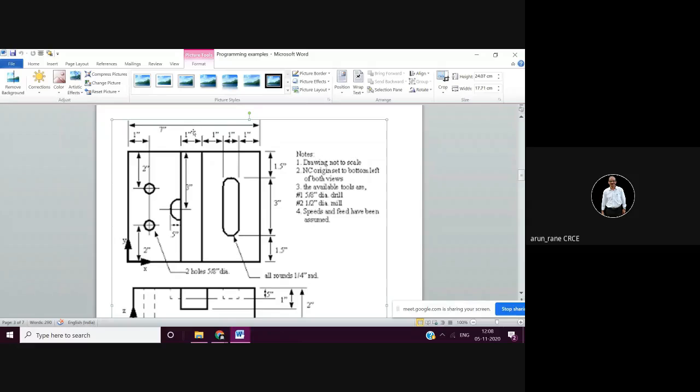Okay. Then I will bring the cutter here. What is this distance? Let us assume that this is given as 3 inch. So it will be now G00 Z 2.2. Then the cutter will come to this position, that is X 3.5 and Z 2.2. Now I'll go down again here. How much will I go down? This much, 0.5.